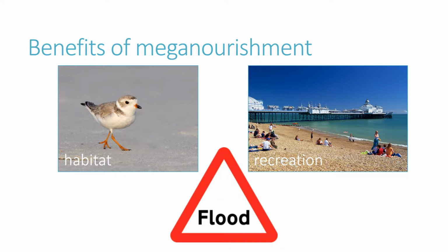Nourishment restores and widens the recreational beach and promotes habitat creation. Structures behind the beach are protected as long as the added sediment remains. When erosion continues, beach nourishment does not leave hazards on the beach or in the surf zone. This is a big advantage when compared with hard beach stabilisation structures, such as seawalls or groins.